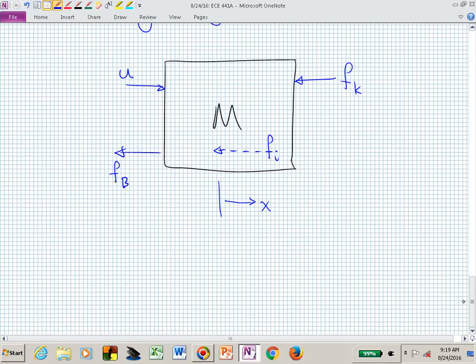Those are all of my forces in this free body diagram. And now I can do my equilibrium of forces. I simply look at those forces and algebraically equate them. All of the ones going to the left I put on one side of my equal sign, and all the ones going to the right I put on the other. Sum of the forces is equal to 0, the algebraic sum is equal to 0, or forces left equal forces right.